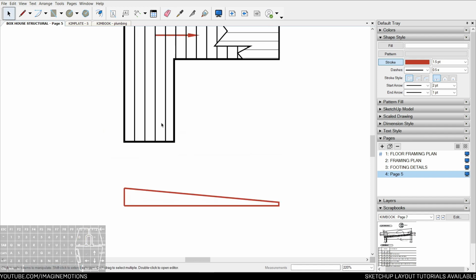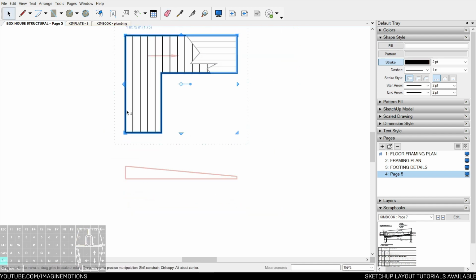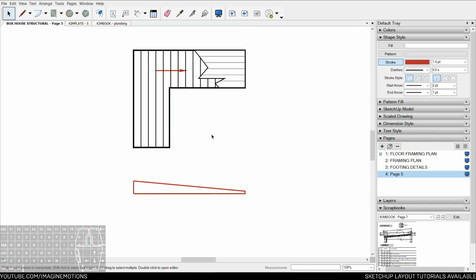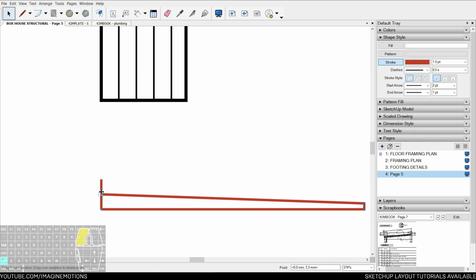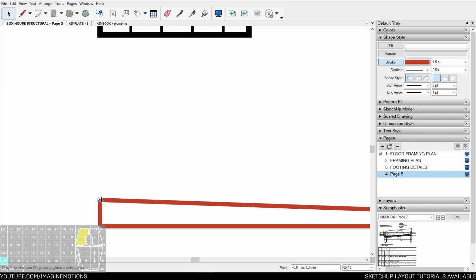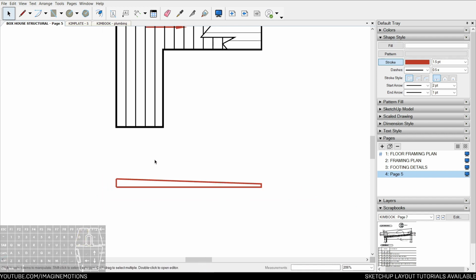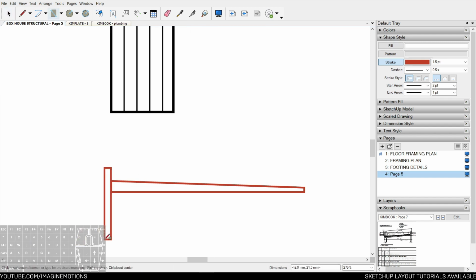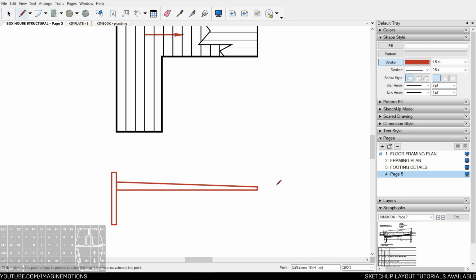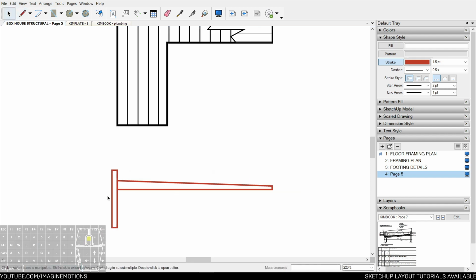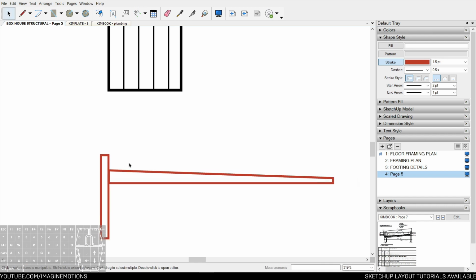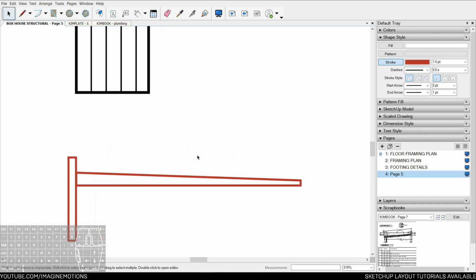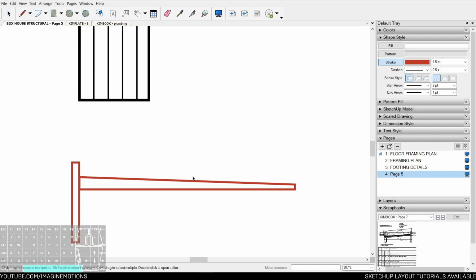This is not the same as the 3D model if you check it inside the SketchUp file. But let's say because of our details, we need to have a slope, so it's not that obvious. But I remember there's a firewall here, and rainwater needs to run off here. So check your building code for the standard offset of the firewall, because the roof should not be extending over the firewall. What will be the use of the firewall in that case, right?